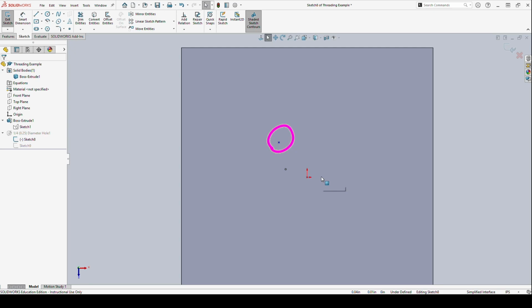So we can always go back and add this, or we could pre-create a sketch with lines that we could then click on to figure out where our piece is. If I wanted it here truly, I could add a couple of dimensions so that I have it locked into a known location. For instance, in this case, my origin point, I could also have it dimensioned from my edges here if I wanted to locate it that way, because those are, again, known positions. But it means that my hole can only be in one place instead of potentially a movable hole, which is not what we want.